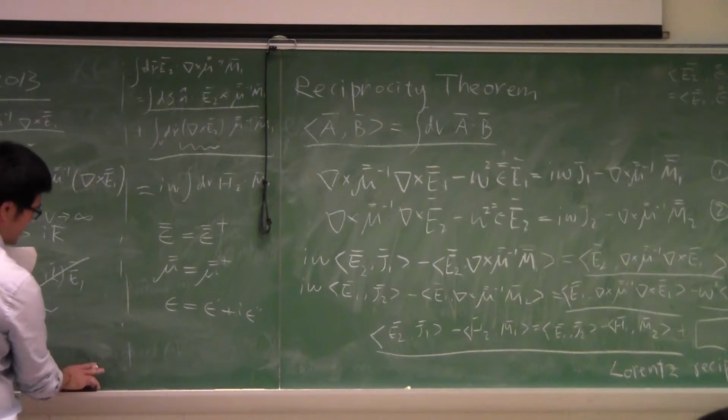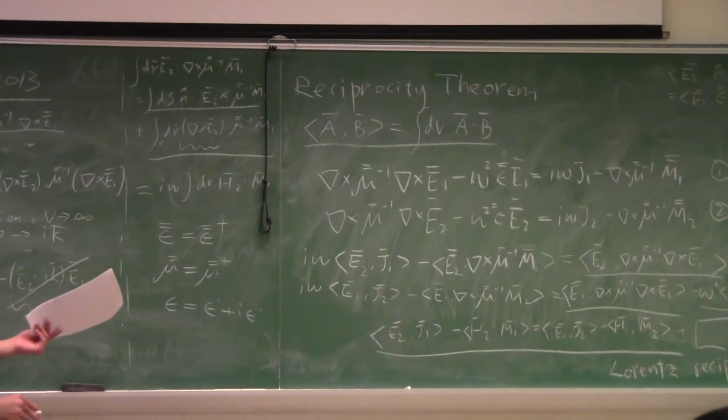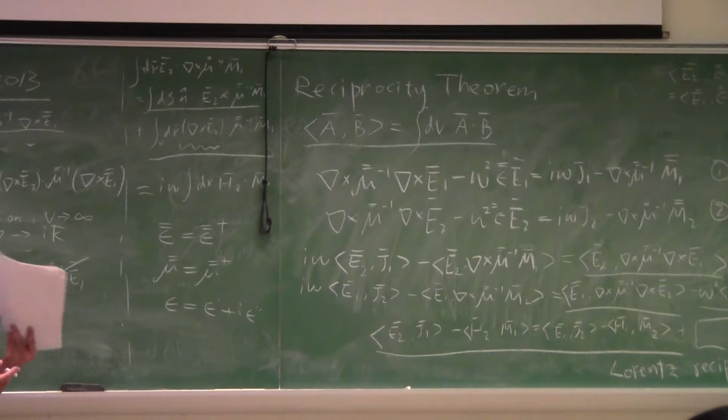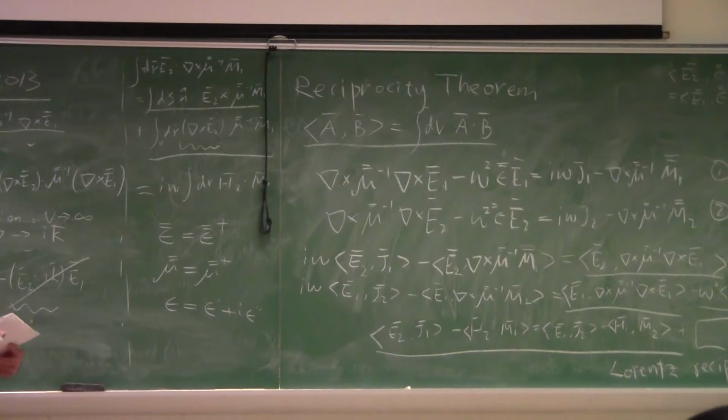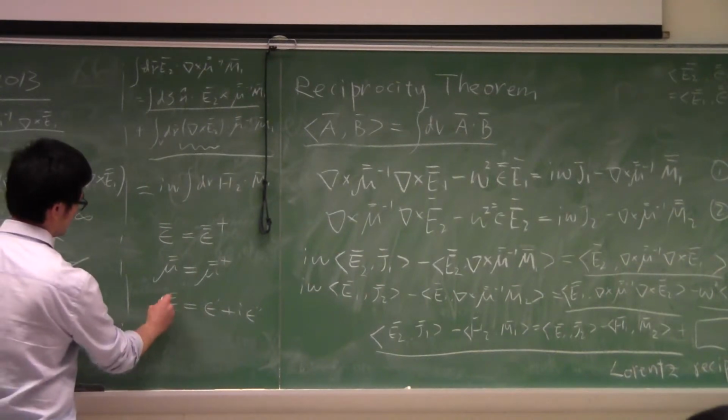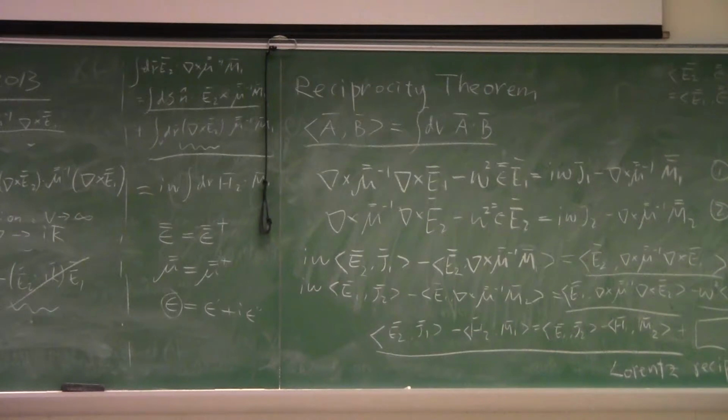So what we can usually see is that a lossy medium can still be reciprocal, but some typical non-reciprocal media usually involve ferrite material and something that can be changed by a magnetic field. So when you see the epsilon or mu tensor has off-diagonal elements which are imaginary, that's typically what we've seen for non-reciprocal material. All right. So, questions so far?